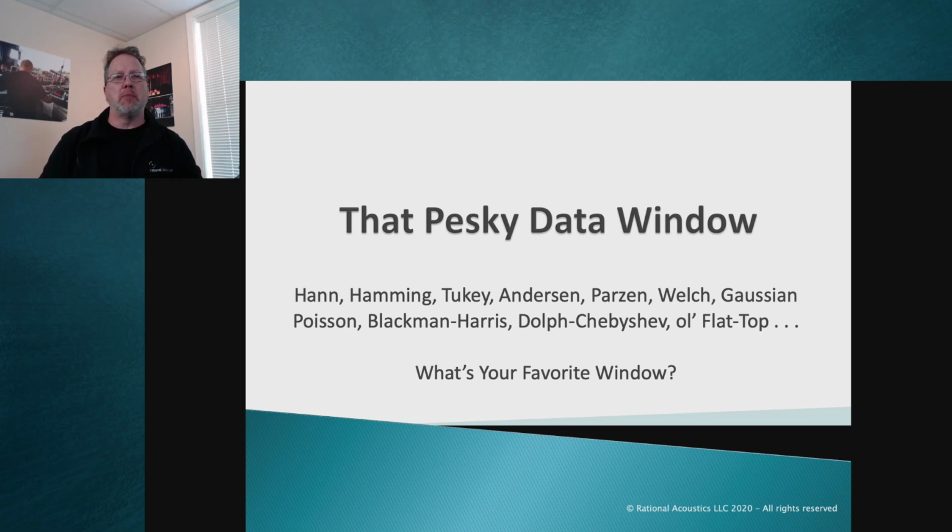Worst case, people go, I don't know, I'll take my measurement without a window. It is important to know about what window you have because we're trading distortions: we're dropping the noise floor and getting rid of problems, but we pick up some other artifacts. So there are reasons why you use one or the other. It really doesn't apply to what we're doing with these types of measurements.